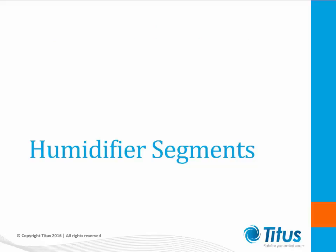Moving into our next segment, ASHRAE Standard 62.1 suggests maintaining a relative humidity of no less than 30% to provide a comfortable, healthy indoor environment. Depending on your proximity, humidity control can mean several things, as well as several different methods of controlling. The next section will primarily focus on the humidifier segment only.